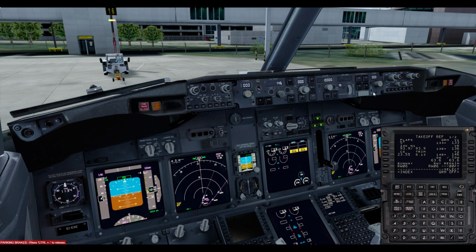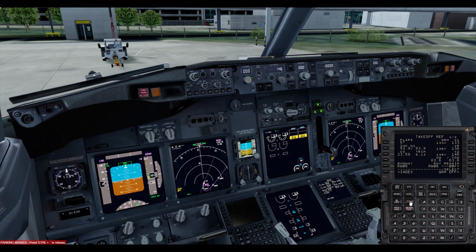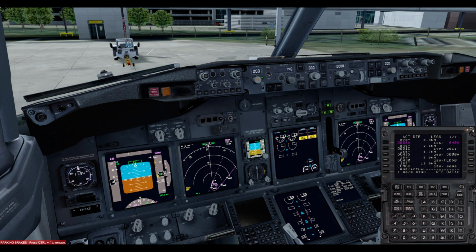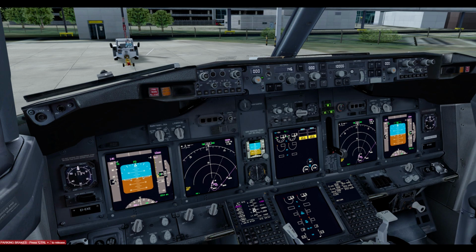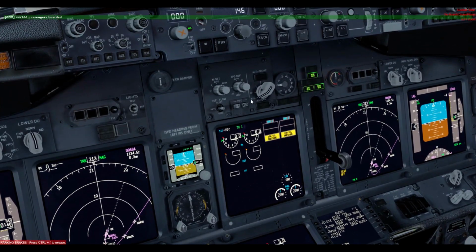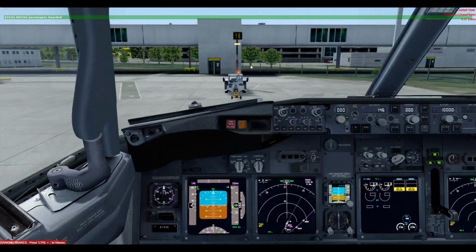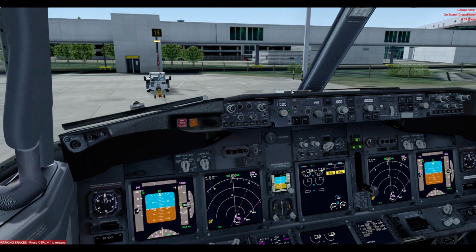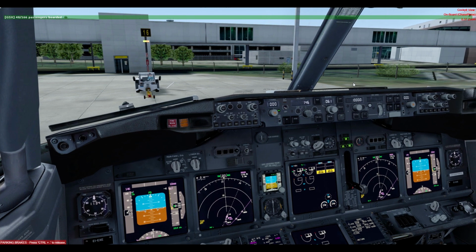And you can also turn on the flight directors. And yeah, then the route is pretty much set up in the plane. There's nothing you have to do in the FMC for now. Some other things we can do is turning the auto brake to the RTO position. If we zoom in, you can see that it says RTO, which stands for rejected takeoff, which makes the plane brake automatically if we end up rejecting the takeoff. And we can set the heading to runway heading, which is about 61 I believe. And initial climb 6,000 feet for today.